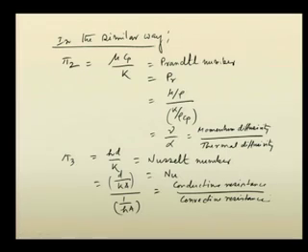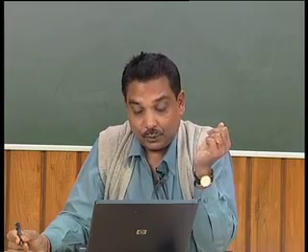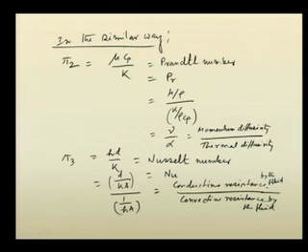So, this is the conductive resistance by the fluid, and this is the convective resistance by the fluid. That gives a more complete definition of the two. Though in short we say conductive resistance to convective resistance, this is what is the Nusselt number. Nusselt number is basically the dimensionless group that gives the heat transfer coefficient term.